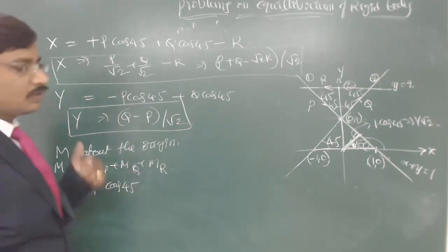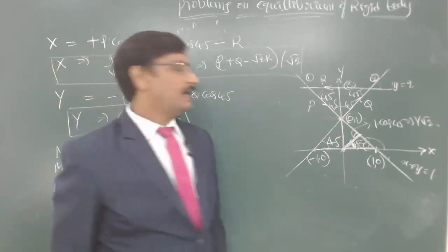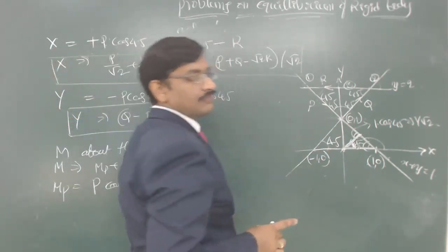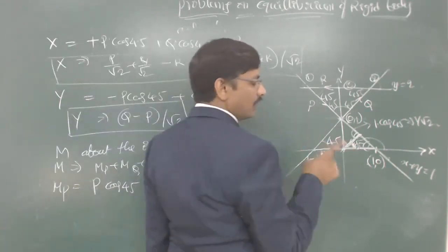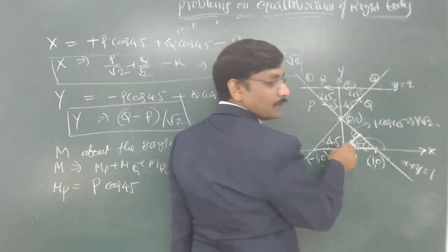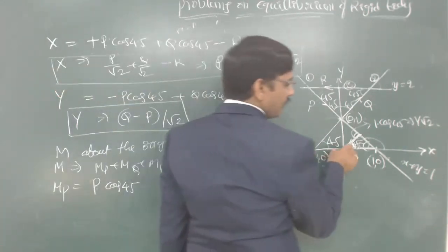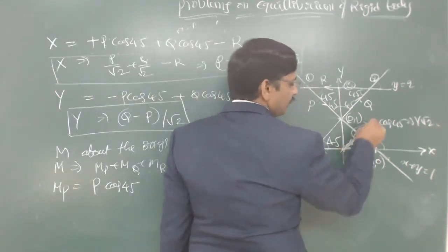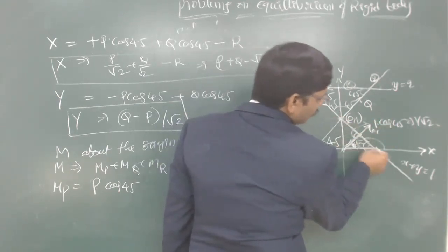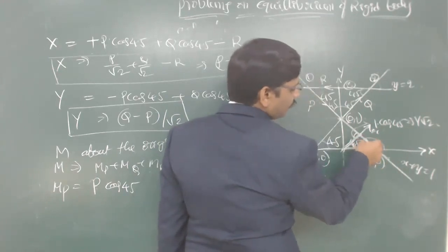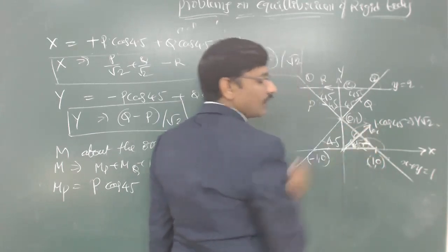Now when you calculate the moment, you have to consider the direction. When you are considering the direction, listen carefully, as it will give a lot of confusion. So I follow a standard convention. From the point about which we are calculating the moment, draw the perpendicular line like this and treat that as R. And then this is the force direction. So draw an arrow there. R also you draw an arrow, and the force direction also you draw an arrow.